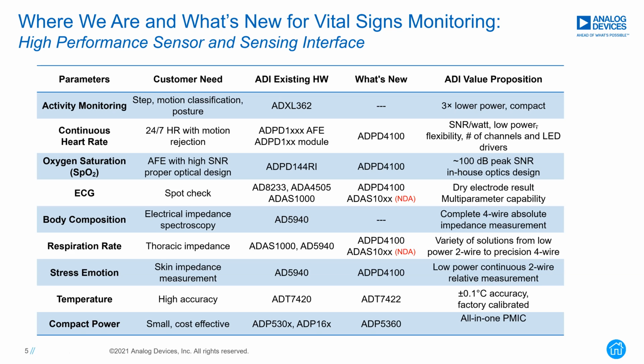you have these new applications which call for continuous heart rate monitoring, where all these photodiodes and LEDs are always on. So the power consumption, along with the SNR, depending upon different types of skins being used, is very important. So parts like ADPD144, and the latest one, ADPD4100, which has an even better SNR and low power performance.